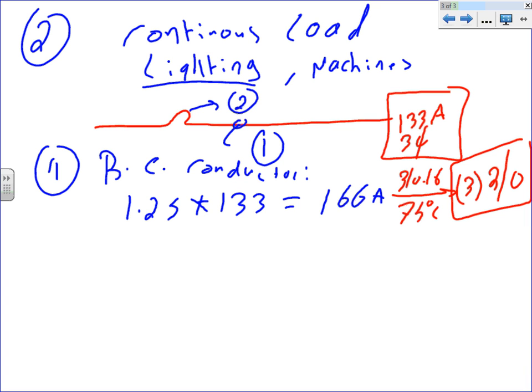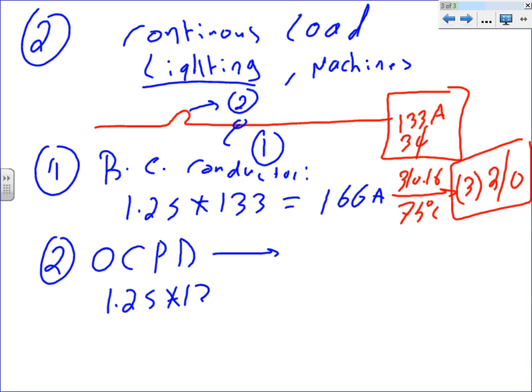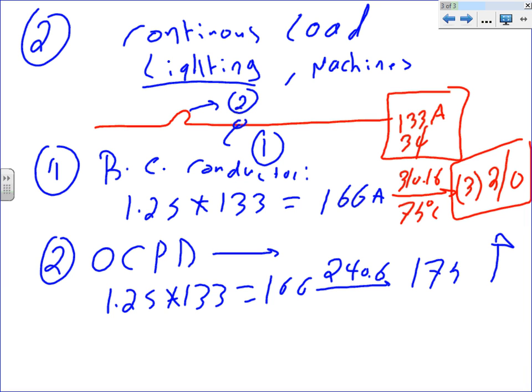We sized the machine. Okay, the overcurrent protection device, the same way, guys. The overcurrent protection device, most likely an inverse time circuit breaker. And you're going to do the same calculation, 1.25 multiplied by 133 equals 166. Take this one to 240.6. And if it's not a standard size, go up. 166, 175, Brooks? Spencer? Yeah. 175? Ben? I'm sorry, Ben. Yes. Everybody is saying the answer, and I'm just, my apology. 175 amp. Any questions, guys, about that?